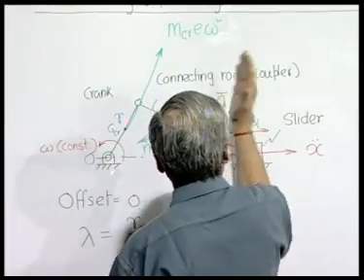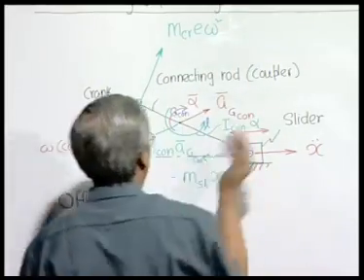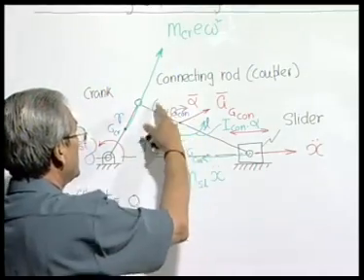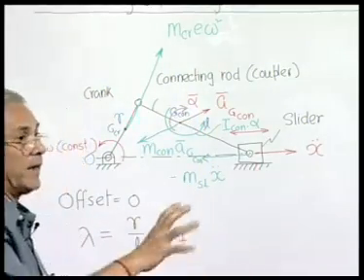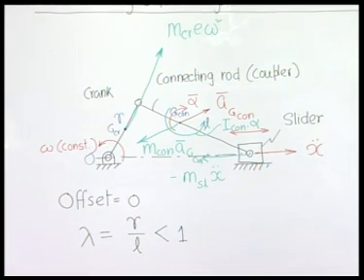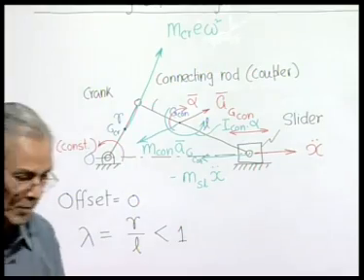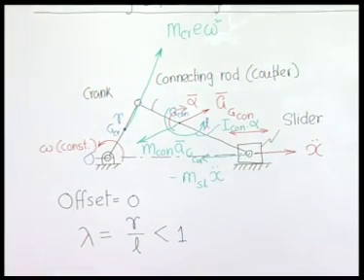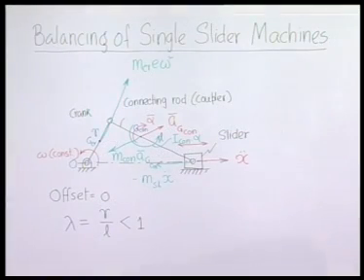The connecting rod is making an oscillatory motion like this between its extreme positions up and down, so this will also produce a moment due to its angular acceleration at any instant. So it is a very complex situation. What we can try to do is consider an equivalent system which is kinematically equivalent, but which is represented only by a purely rotating body and a purely reciprocating body.